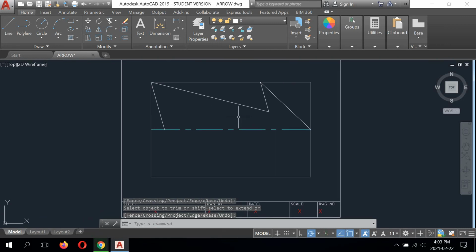Now, obviously, when we look at the arrow, this is a symmetrical drawing. This center line represents symmetry. So what are we going to do? Are we going to draw this all over again, the same underneath? No, we're going to mirror it. We learned how to use the mirror in the W drawing. We're going to practice it in this drawing, is what I should say.